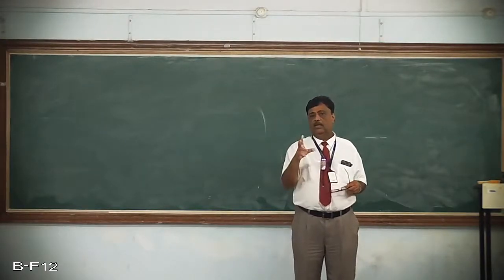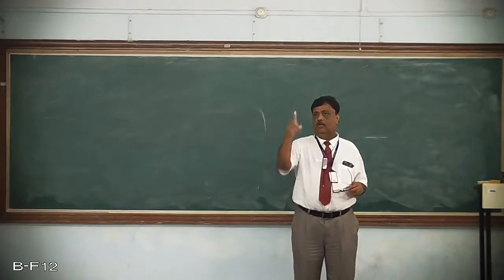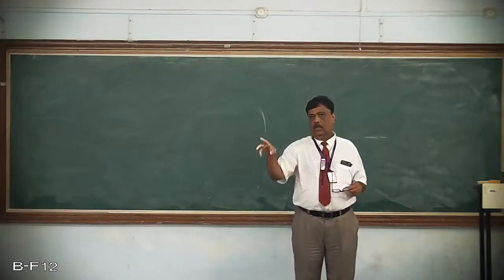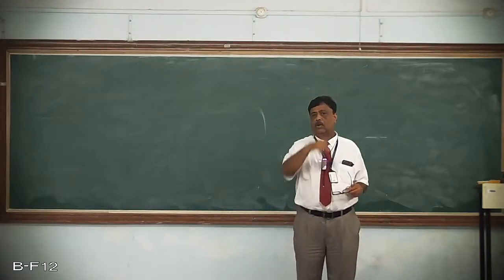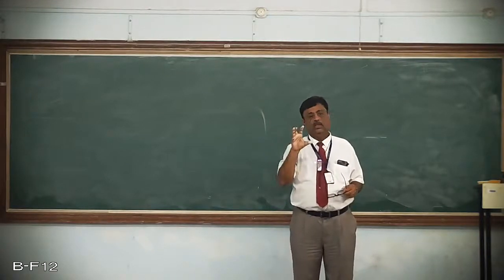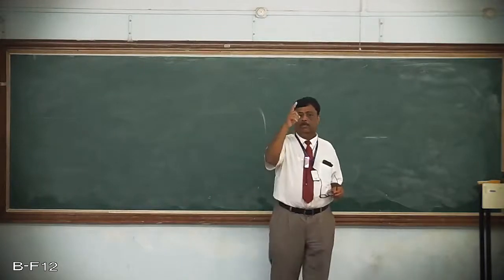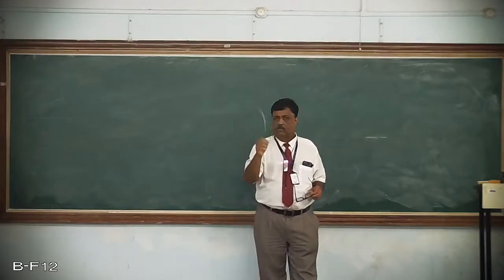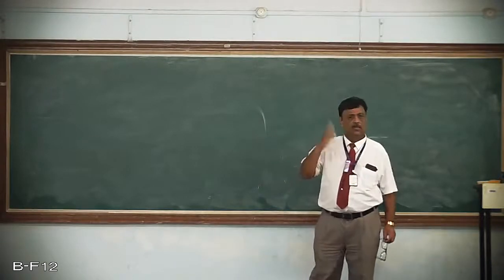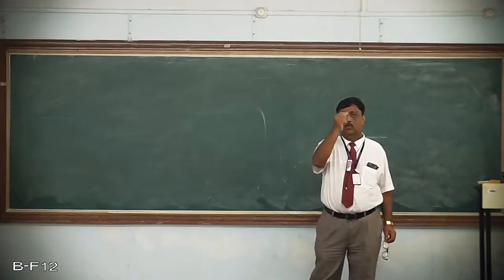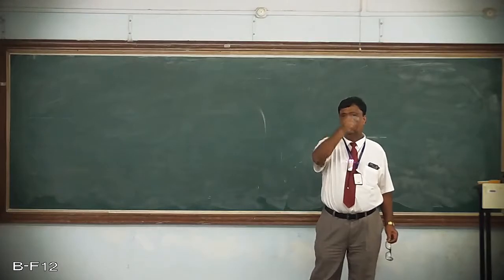What I would like to say here is, if you have an approximate curved boundary, or an irregular shaped boundary, and you discretize it with these types of elements, because of this straightness, however small an element you use, the number of elements will definitely go very high, because you have to close those curved portions by straight portions.